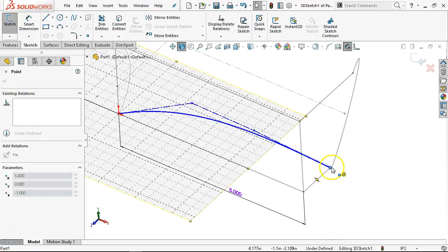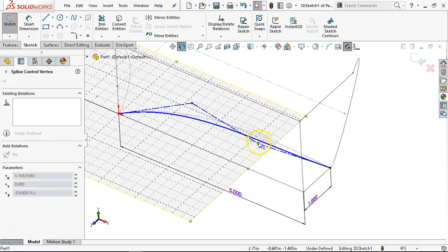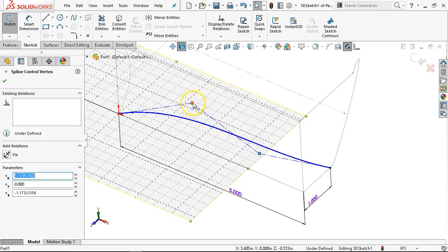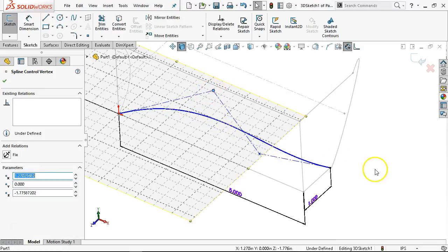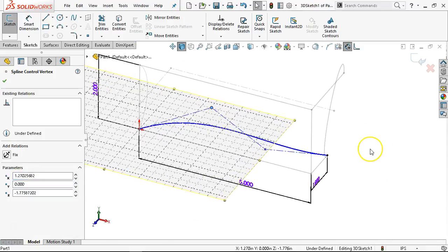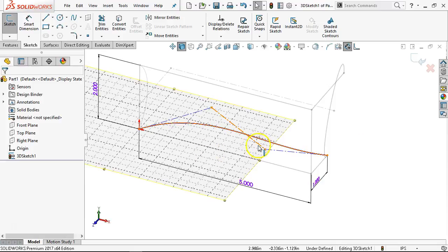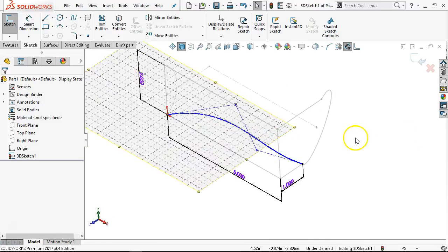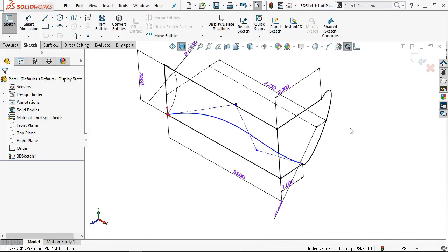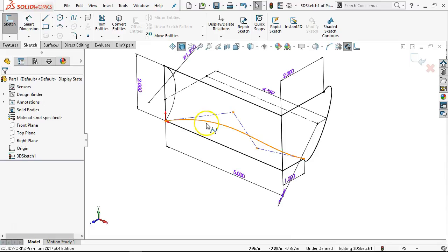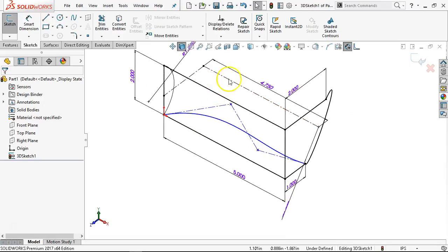Did it connect? No, it didn't connect. There we go. All right, so the style spline is going to let me drag those construction lines and get that little bit of wave. Again, dimension back to those points, where before we had the handles and could stretch and shrink. Now, not so much. Just a little bit different.